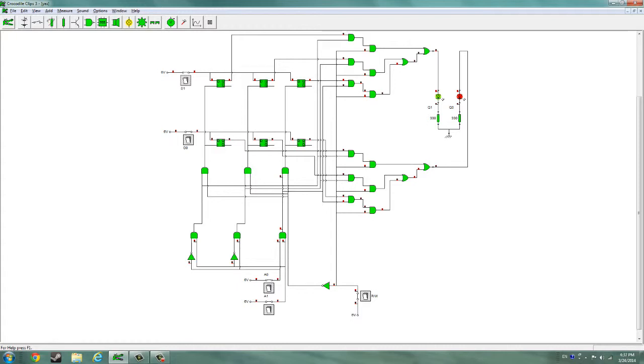The preset and clear inputs must be connected to the positive terminal to make the circuit asynchronous, meaning independent from the clock. When the switch is open, current flows through the clock input of the flip-flops, and since our commercial D flip-flops are positive edge triggered, it stores the values of D0 and D1 to the flip-flop indicated by the address leads.